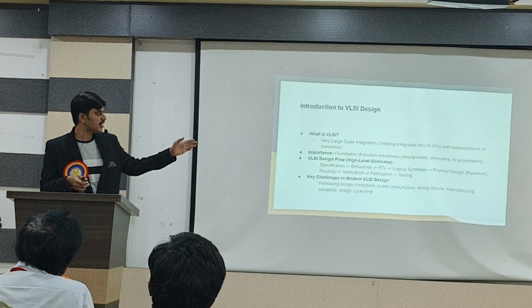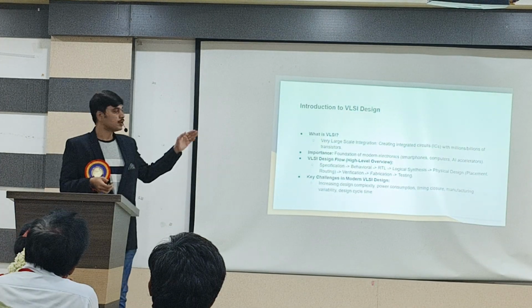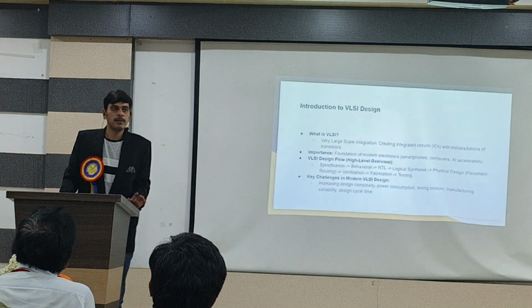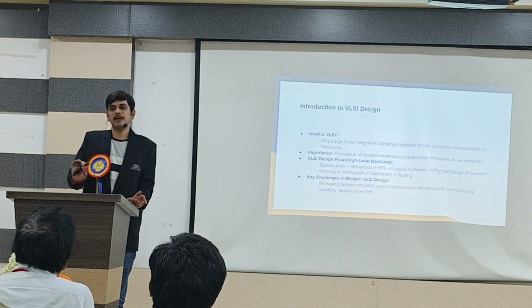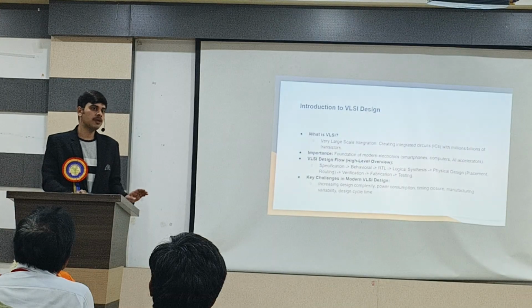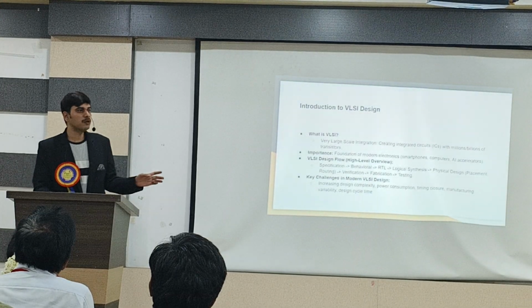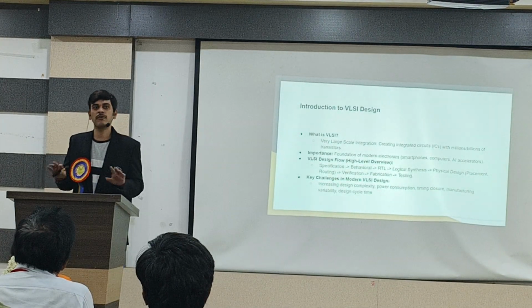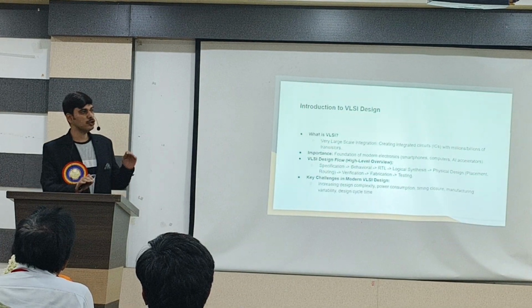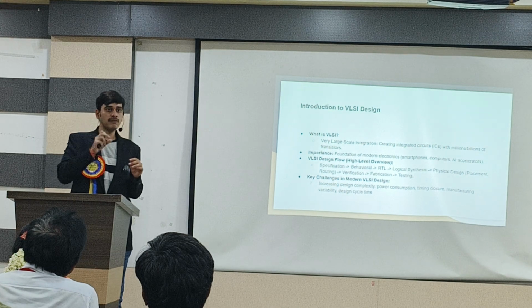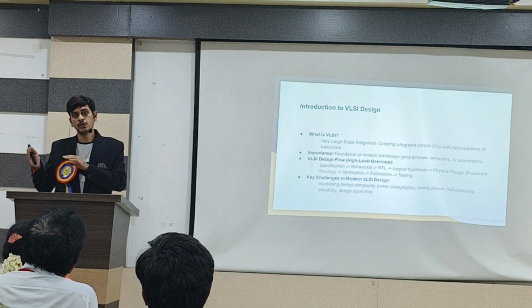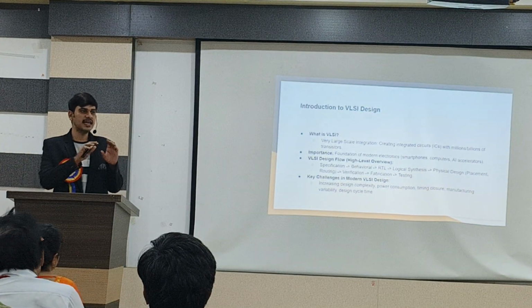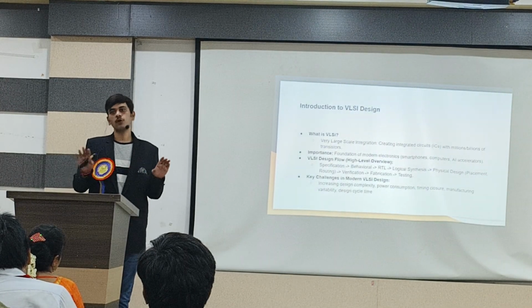Physical design, from synthesis onward, is the backend, and before the RTL it is the front end. In physical design, we also have timing. Timing is the most critical part of the entire system, because even if you design the best code and have the best application running on the system, if timing is not closed, it's a waste, because it won't work. You have heard about metastability. Whatever we code, finally it's 0 or 1. If the logic level is between 0 and 1, the system can't predict it and goes into a metastable state. So we do timing closure, and if we don't, even if the system has its entire functionality and verification passed, the system won't work.